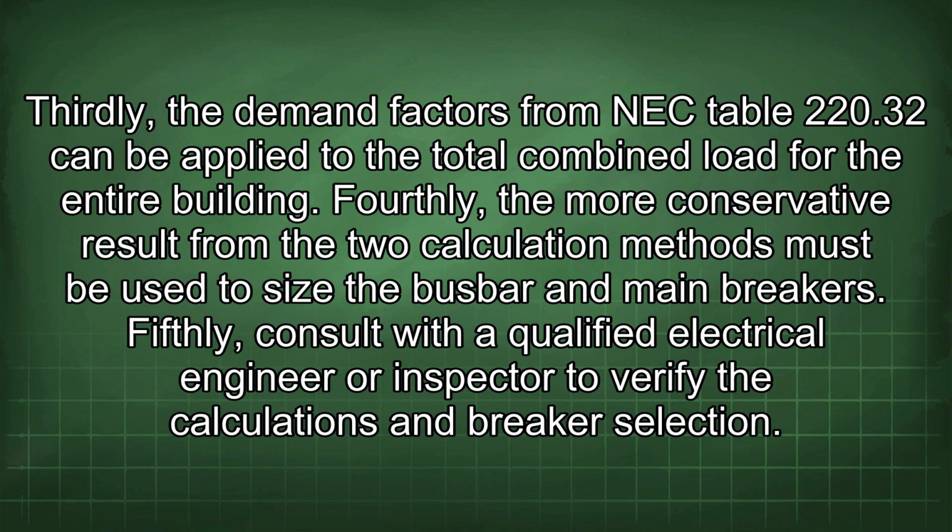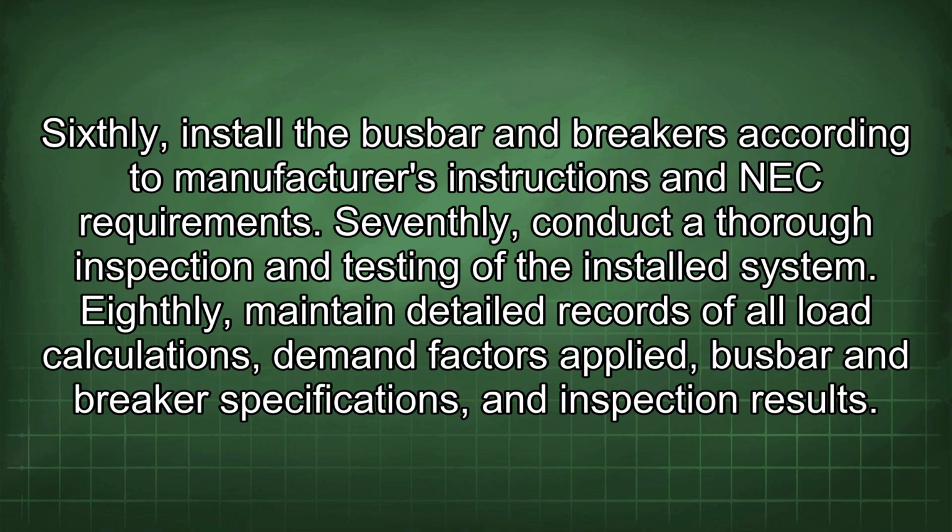Fifthly, consult with a qualified electrical engineer or inspector to verify the calculations and breaker selection. Sixthly, install the busbar and breakers according to manufacturer's instructions and NEC requirements. Seventhly, conduct a thorough inspection and testing of the installed system. Eighthly, maintain detailed records of all load calculations, demand factors applied, busbar and breaker specifications, and inspection results.